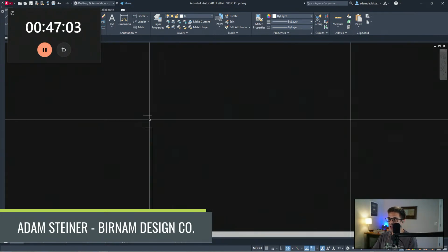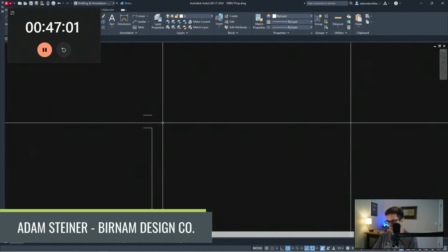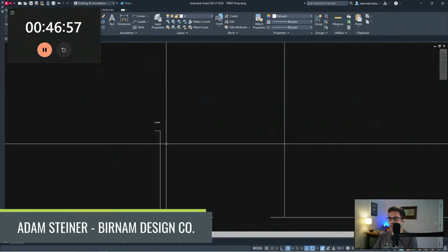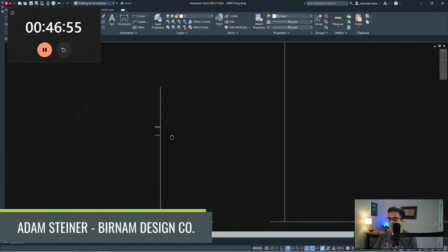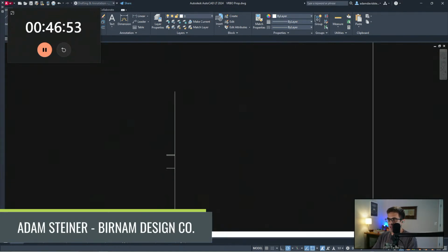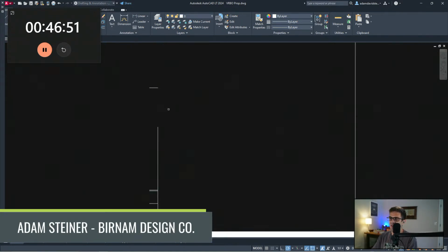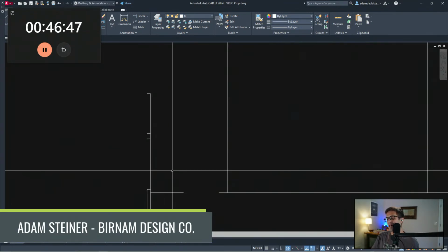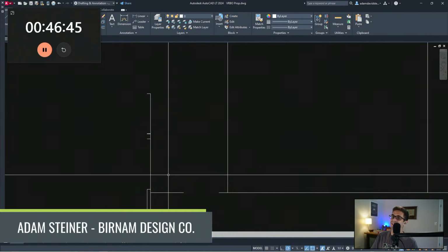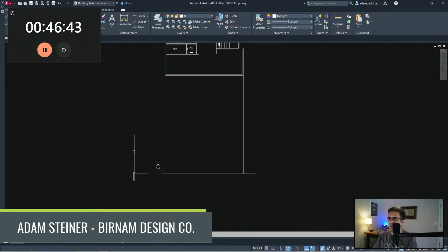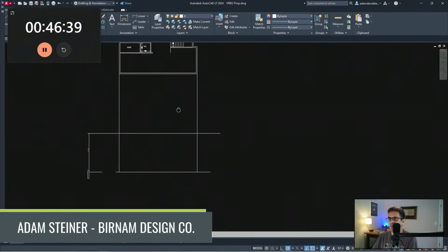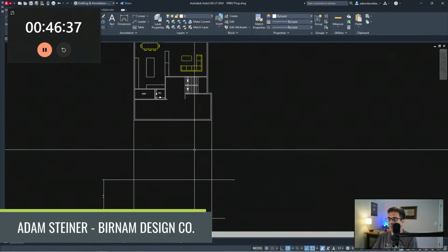11.875. We're going to do TJI for joists. TJIs work because it gives you options. Because you can always flex down to 2x12s if you need to, or go slightly up if you need to, do like a 16, potentially add a tread. But they also have great spans on them. They're expensive though. They're on the expensive side for sure.